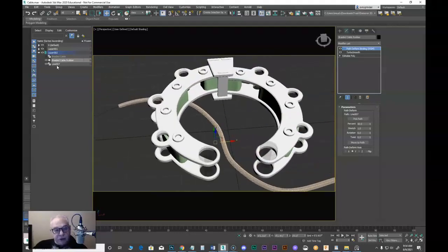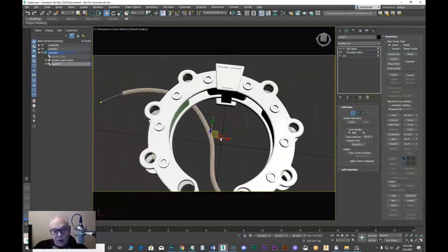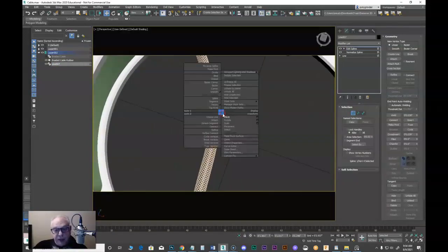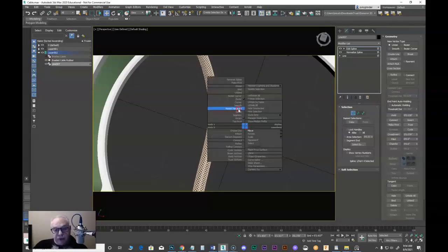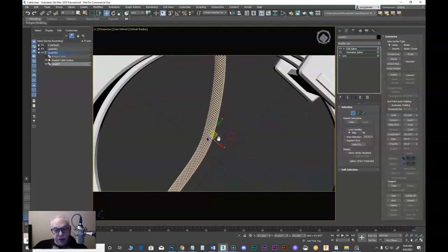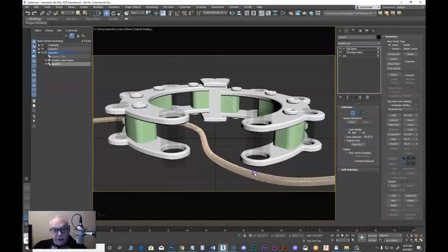You know, and I can do other things too to this spline. Everything is smooth right now, but if I needed some kind of movement, I can always turn this into a Bezier, and then I have my Bezier corners that I can use. But you do get a thing where you can end up stretching the piece, so you just have to be careful with that. I have a tendency just to leave everything with smooth, and then if I need more, then I just add some more points in there. And that's braided cable 101.